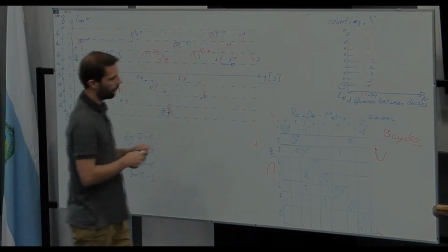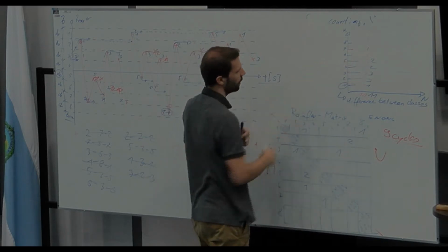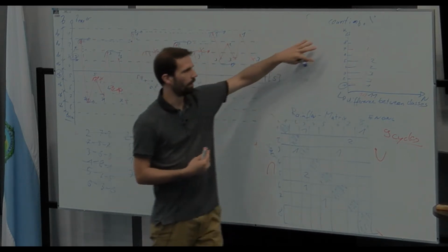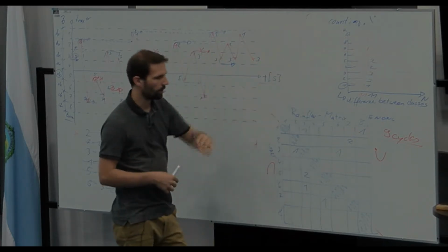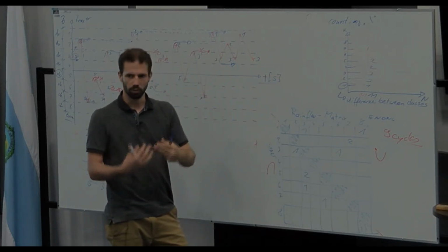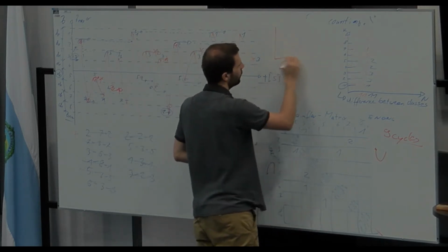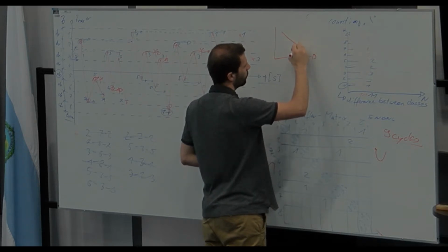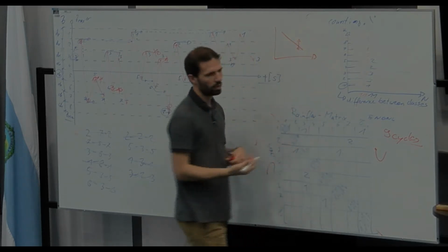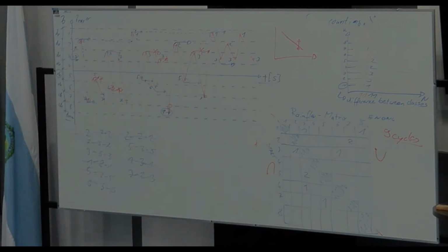And also at the same time, we now can go and define our load histogram, but also give some information, if it's really wanted, about the R value. And as we have seen, the R value gives us the information on the stress ratio, so here about the resistance curve and also about the damage onto our structure.